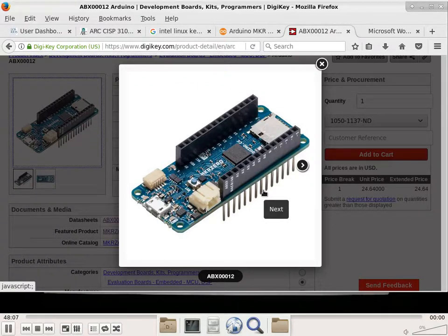Okay, it makes a lot more sense for the chipset just to tell you about the magnetic flux strength and give you a range of numbers that is a power of 2. 1023 is the max on this axis and on this axis. So your driver code is now going to the chipset and say, okay, I know your conversion is done. Tell me about the magnetic flux strength in 3D. Usually now it's 3D so that your device can tilt and rotate in any direction and it will still be able to give you the direction.